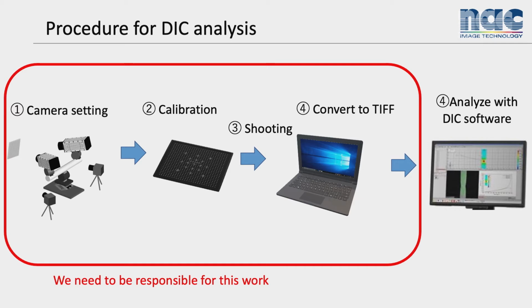Fourth, convert the image data to TIFF data. DIC software can analyze only TIFF data, so we need this work. Fifth, analyze with DIC software. When we make a demonstration with a DIC partner, we need to be responsive from setting up the camera to transferring TIFF data. We will share with you this process for DIC application from now.